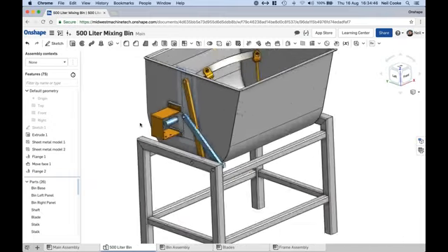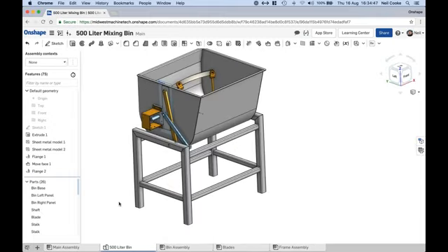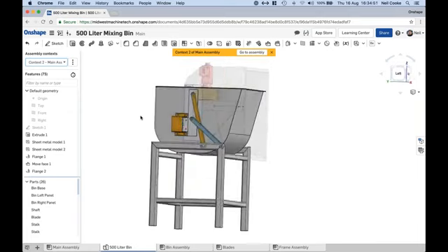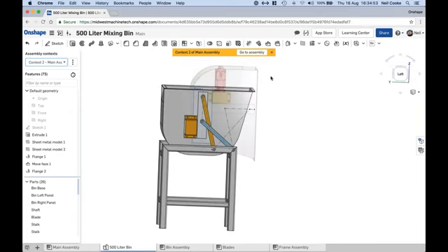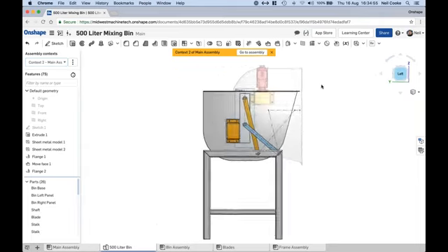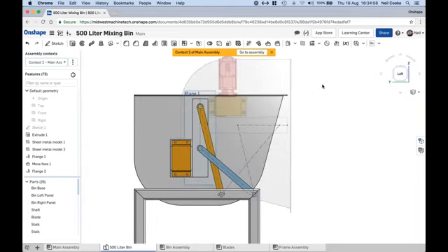Okay, and again you can see that even though I actually move the assembly, the context remains fixed, and that is really a snapshot in time. So it means that you don't have to worry about this thing messing up at any particular time. Okay, all right. So that's how you create a two-position linkage. Again, using in-context editing. I apologize for the first sketch. Like I say, I kind of messed that up.